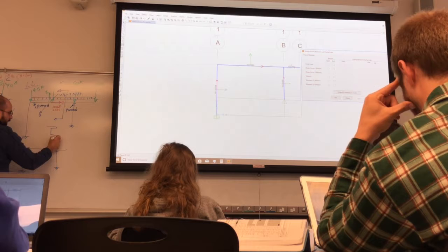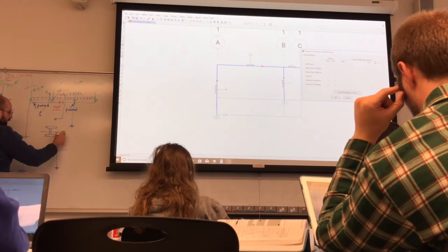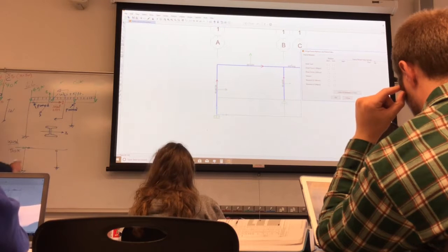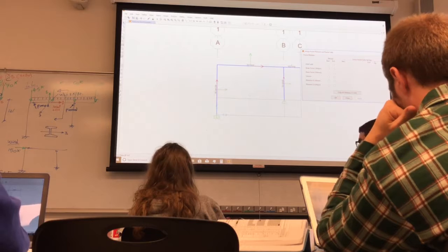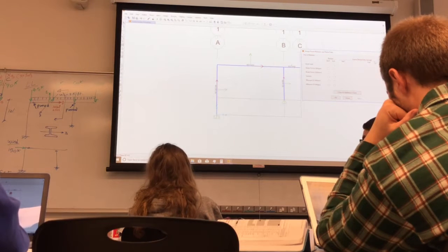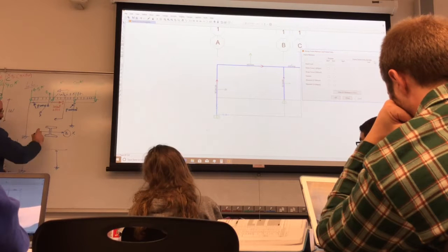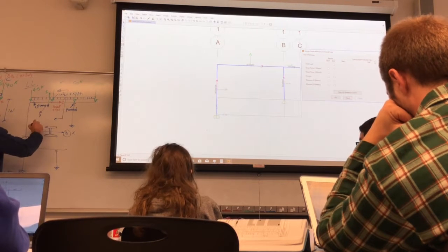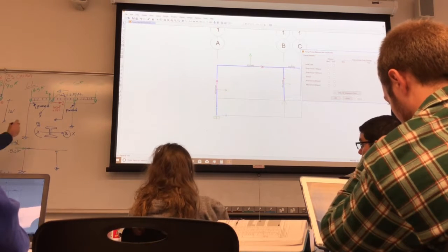You'll see the beam is a W21 by 44, and then you'll see the arrow 3 will be in this direction, right? So what it means now is that 3 is the x-axis. So when you're dealing with moment about x, that's the M3. SAP calls it M33.